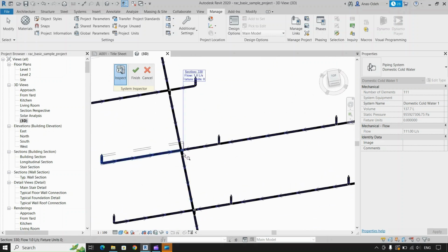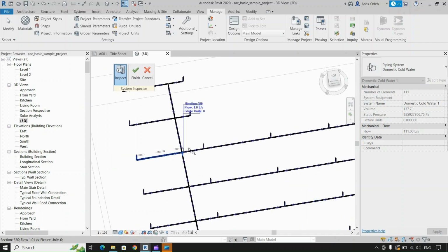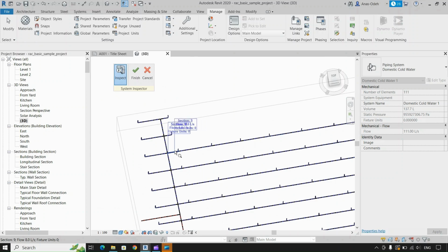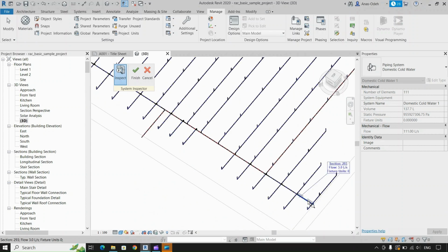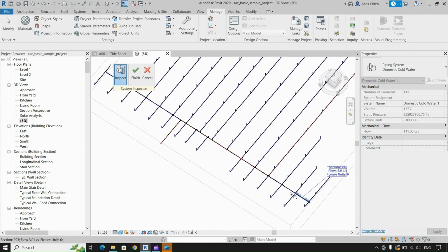If you encounter an issue, you might divide the network or manually adjust the sizes of the incorrect sections at the end. For instance, if the pipe holds 3 sprinklers, the flow value has to be 3. This statement is correct for all the branches in my network.